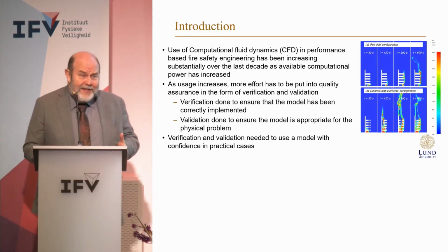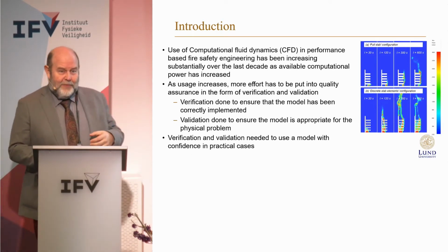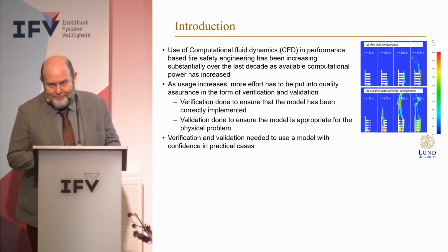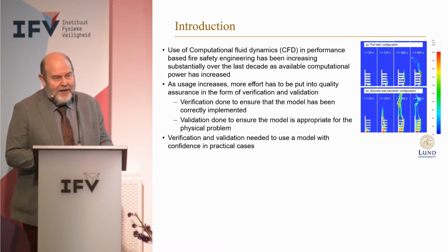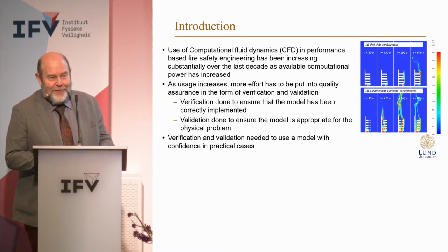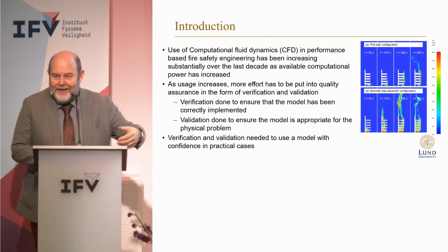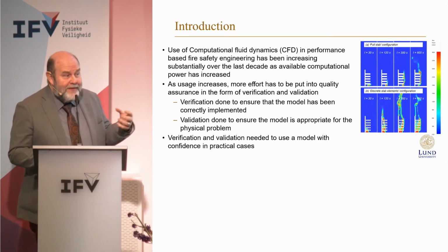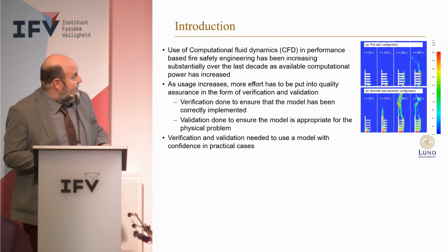The other thing is the validation, which is that your model is really appropriate for your physical problem. Here it's the same. I gave a very simple example, 3 + 2 is equal to 5. But if you want to know what 3 times 2 is, which is 6, and you use a calculator that only does addition, that will not work either. You use the wrong type of model, because your model can only do addition and not multiplication. So this is, in a very simple way, the difference between verification and validation.